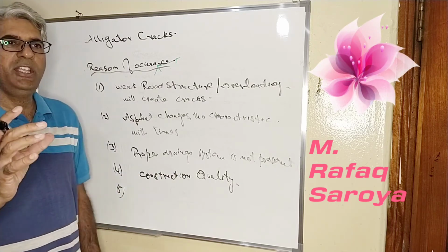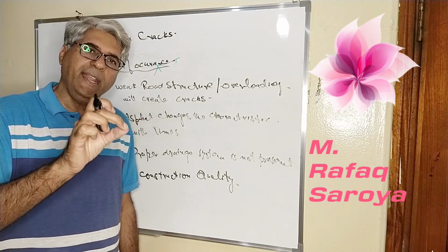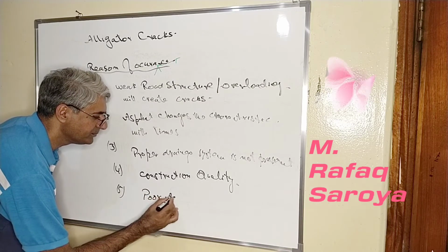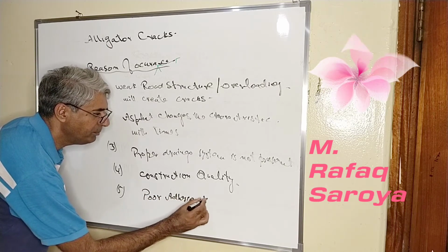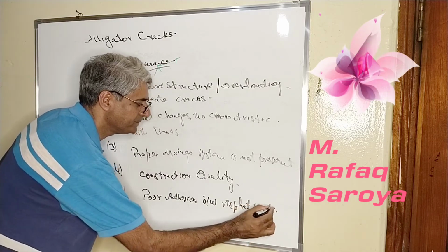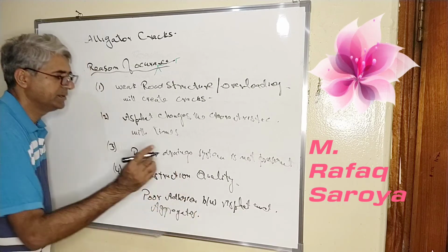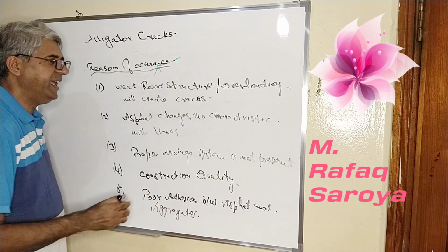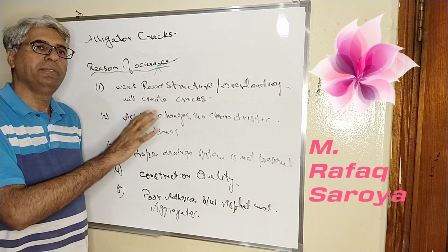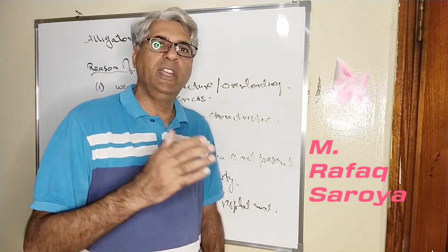Next, there is the relationship between your asphalt and aggregate. When there is poor adhesion between asphalt and aggregate, poor adhesion will also lead to the occurrence of this type of failure on the asphalt surface.